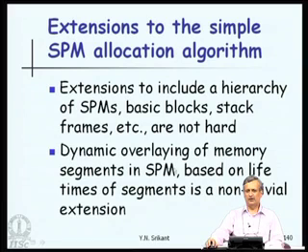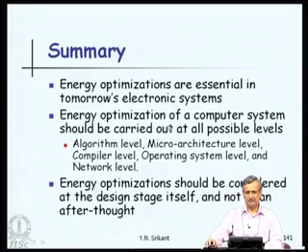However, if we want to do dynamic overlaying of memory segments in a scratch pad memory based on the lifetimes of segments, this is non trivial. In other words, one small part of data or instructions comes into the scratch pad, stays there for the lifetime of that particular segment, and then once it is of no use anymore, some other memory segment is brought into the SPM and used. Such dynamic overlaying of memory segments based on lifetime is definitely a non trivial extension, and that is a nice research topic for the future.